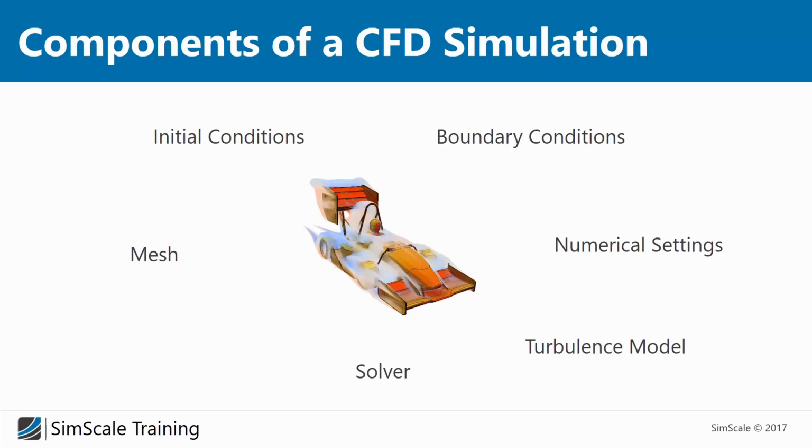And maybe one general thing before we talk about meshes. At the end of the day, CFD can mean computational fluid dynamics or colorful desktop. What I want to point out with that is that a CFD simulation can also give you totally wrong results. And it's very important to understand when you can trust the result and also how to make sure that your result, your approximation, is exact enough for your problem.